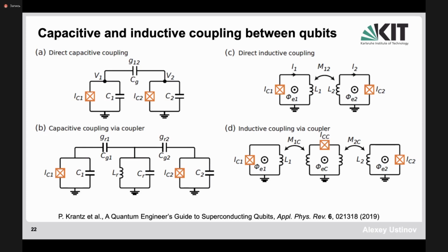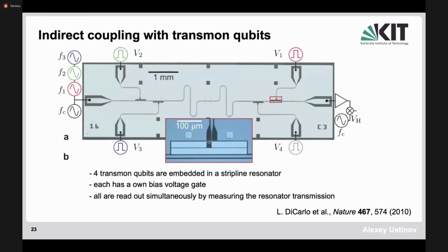It means that different pairs of qubits doing different jobs will interact with each other when you manipulate only one pair and do not pay attention to the other. Therefore one has to calibrate the multi-qubit circuits to avoid these crosstalks. It really becomes rather complicated. We'll talk about this when we discuss scaling up of the qubit circuits.